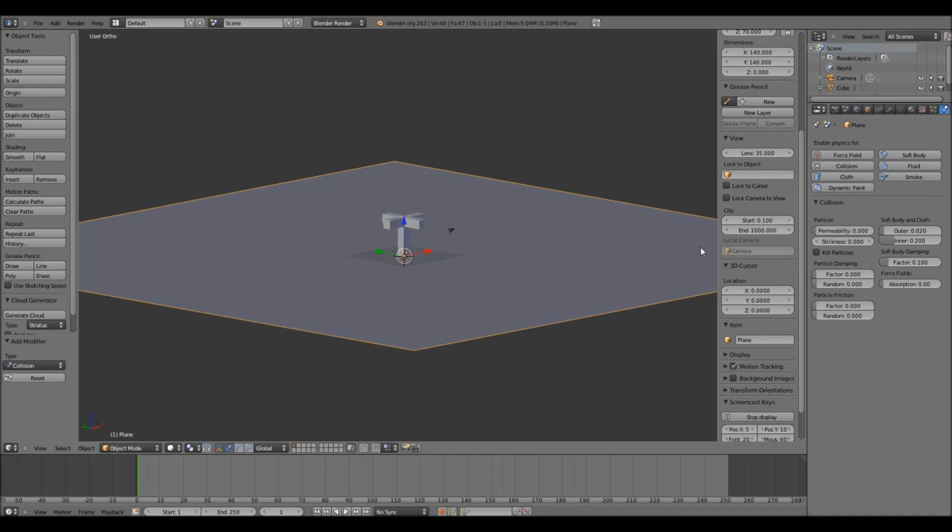Since we are talking about fluids, the fluids don't have to jump off from the floor, so let's go for something like 0.9. So still the particles will hit the floor and maybe jump just a little bit as the fluid would behave. So let's add some randomness of 0.15, and that would mean that some of the particles will jump higher or lower than the other ones. And friction defines how the particles would behave on the surface of the object.